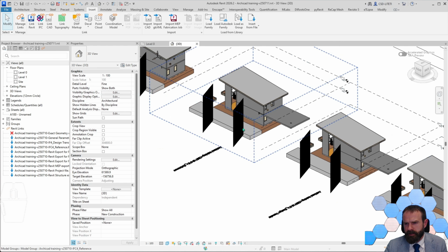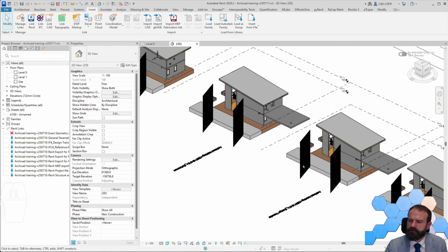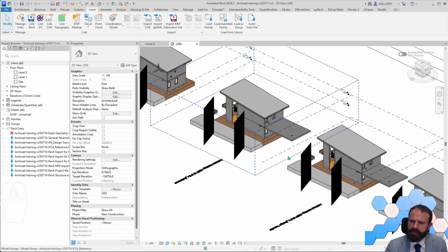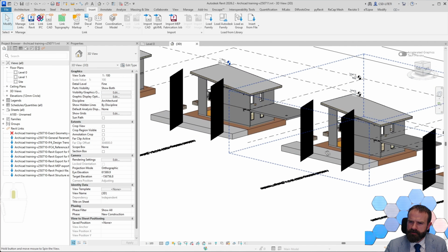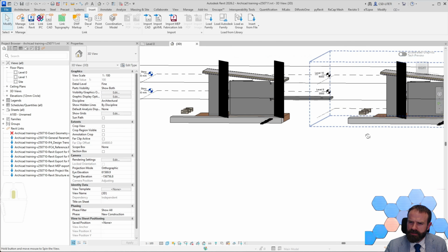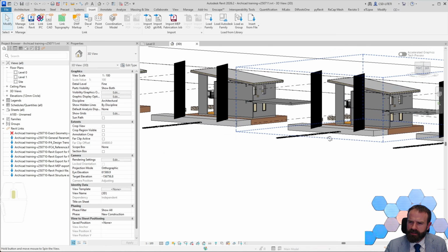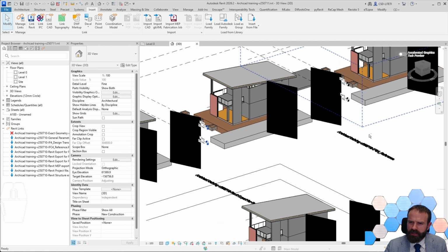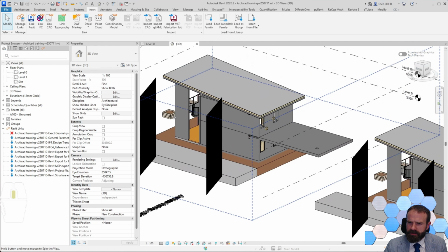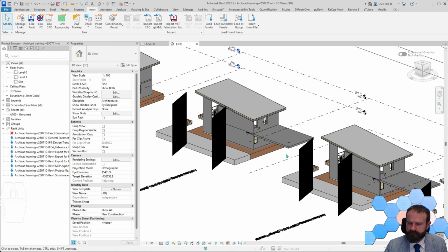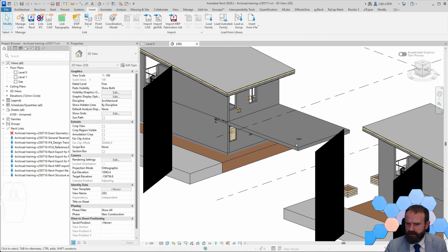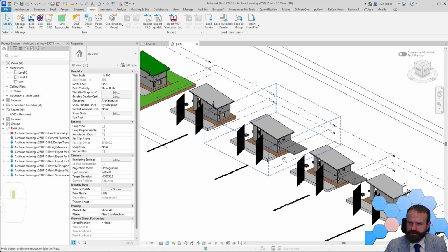So it means conversion of IFC4 format, which was made from ArchiCAD, is in bad shape and can lead to wrong design. And please be careful using this option.